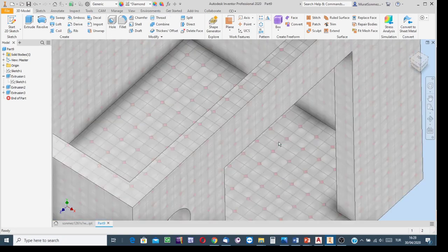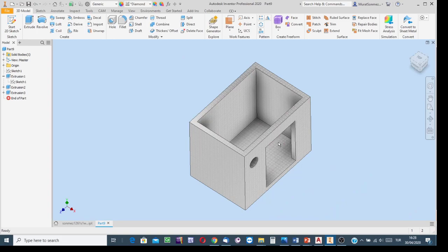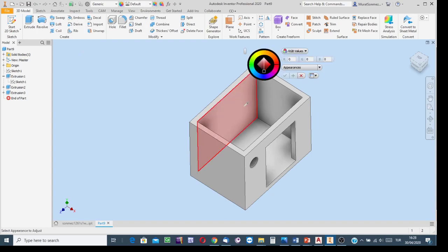For all the surfaces you see, we have such a cover. So if you're going to paint not all surfaces, but some of them, then click on this button, or in the classical method, indicate the surface, right click, and then find the color or surface effect option, and then click on OK.